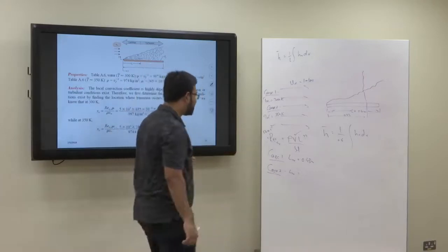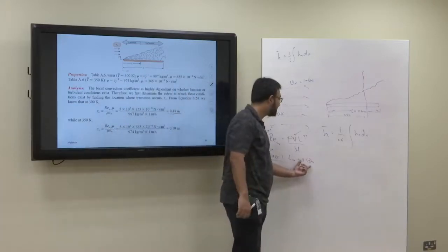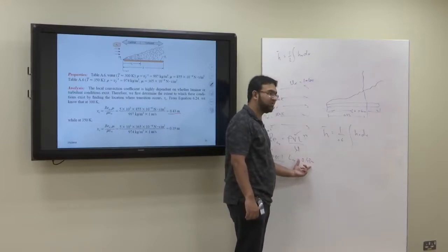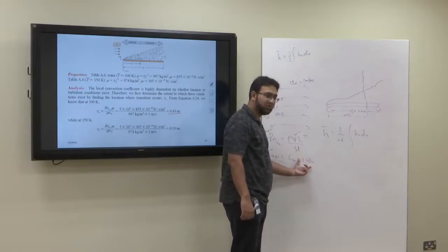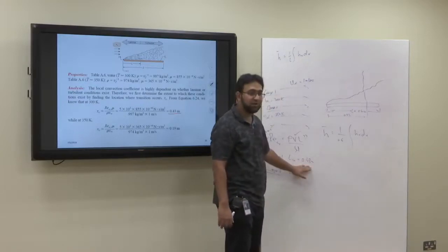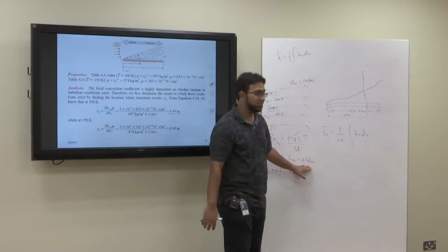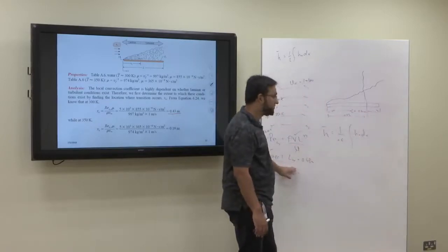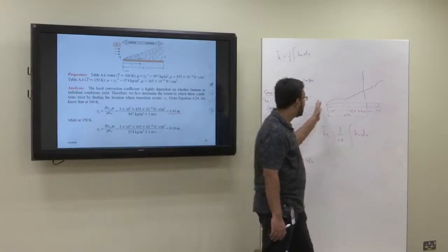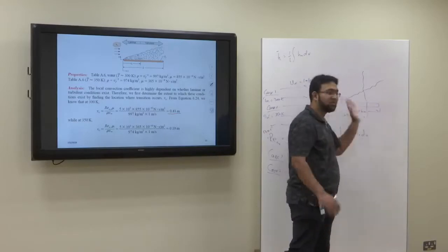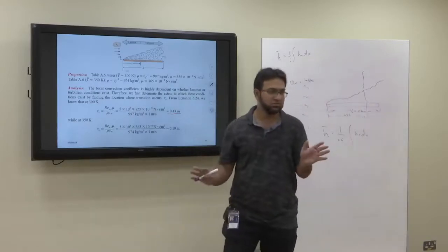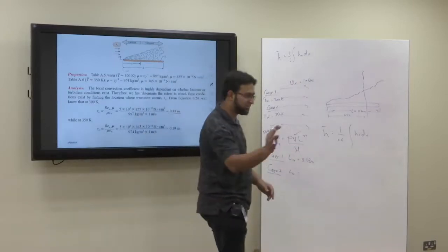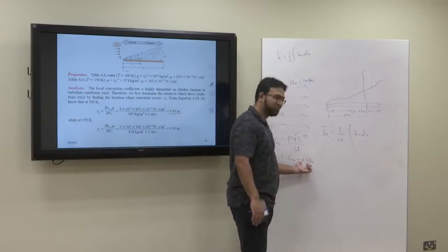Suppose the length comes out to be 0.7 here. What do you think? Does the flow remain laminar, or turbulent, or what would be the case? If after putting values the answer comes out 0.7, that means your complete length is 0.6 and the critical occurs at 0.7, so over the entire length range it remains laminar and never goes turbulent. Suppose, it's not going to happen, but suppose L critical comes 0.